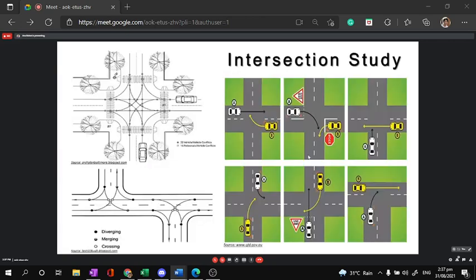Okay, so intersection study is another kind of application. This is only for any junction, no? 4-leg, 3-leg, and so forth and so on. In intersection study, we're not just studying the traffic signal, we're also looking at accidents on the road, especially sa intersection. So to avoid intersection accidents, we have to look at the design of the intersection in such a way we look at conflicts. So these points here, 1, 2, 3, 4, 5, these are points of conflict. Conflict, kung dili ma-mitigate, bangga. So accident. So an intersection is really prone to accidents.